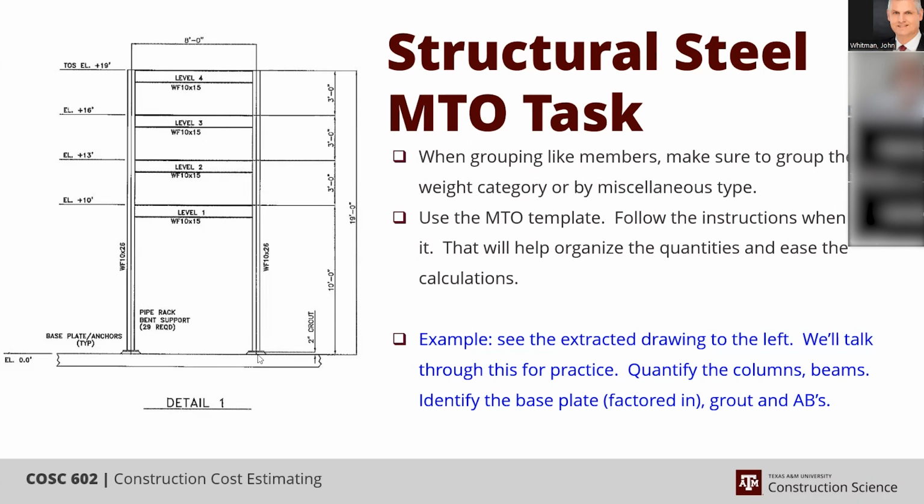And the purpose of the grout is because when you think about it, when you set that beam down and tighten that base plate, it's already level because it's sitting on shims. However, by filling in that base plate with non-shrink grout, then as the shims slowly compress over time, the grout will then start sharing the load slightly, but the load's still primarily on the shims.